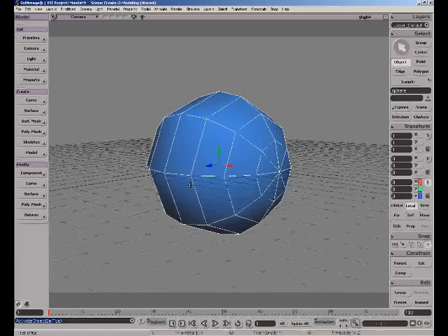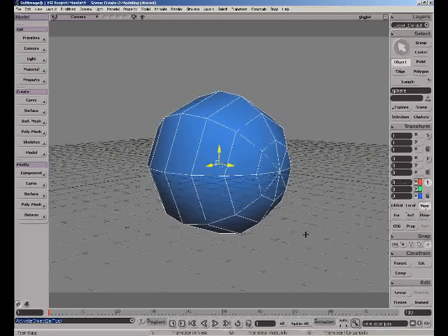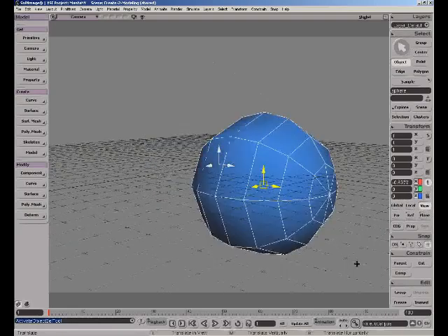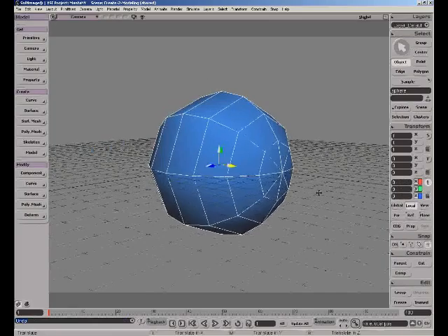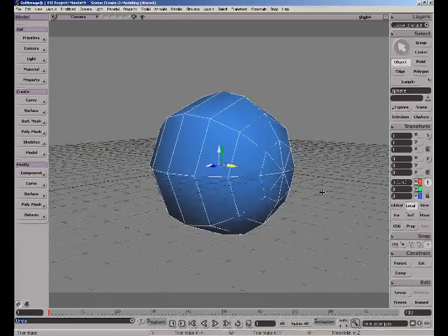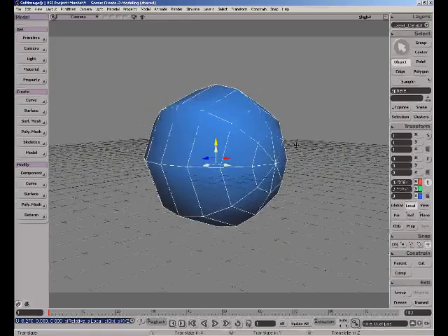object mode. This is actually very important, especially when doing modeling or just translating your model around, or moving your model around inside the world. If I am in, say, translate view mode, and I've got my object selected, I'm going to move the entire object around. And you can see it just moves freely around inside my camera viewport, which is the view mode. If I go into local mode, it's going to use the local axis of this particular object to translate it around. So now if I hold down the left mouse button, it's translating only in X. If I move the middle mouse button, it's translating only in Y.